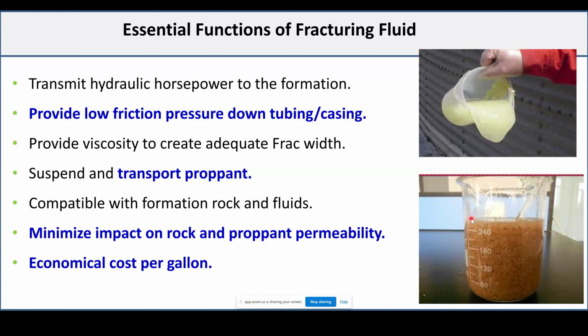So you have a guided perforation, and the perforation will allow all the fluid to go through. But the casing itself, because of the strength of the steel, is too difficult to break. So fracking the formation usually takes a much lower pressure compared to fracking the casing. Hopefully I understood your question right. If not, please rephrase it one more time.